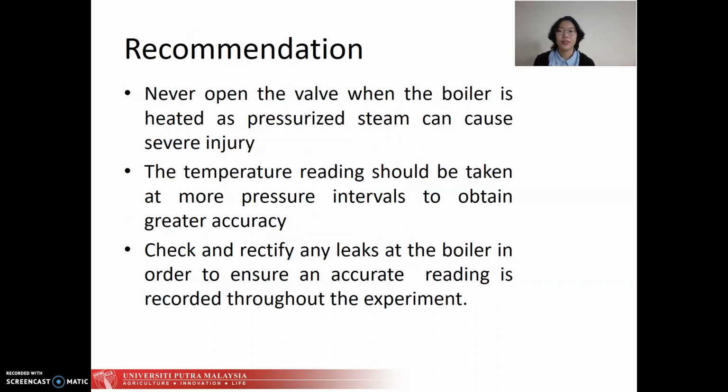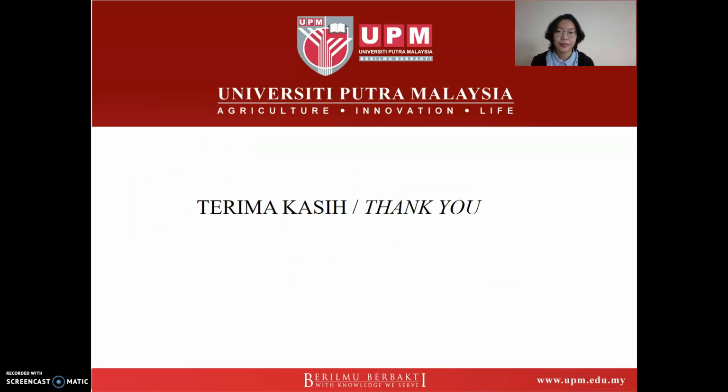Recommendation: the first one is never open the valve when the boiler is heated, as pressurized steam can cause severe injury. The second one is the temperature reading should be taken at more pressure intervals to obtain greater accuracy. And the last one is check and rectify any leaks at the boiler in order to ensure an accurate reading is recorded throughout the experiment.